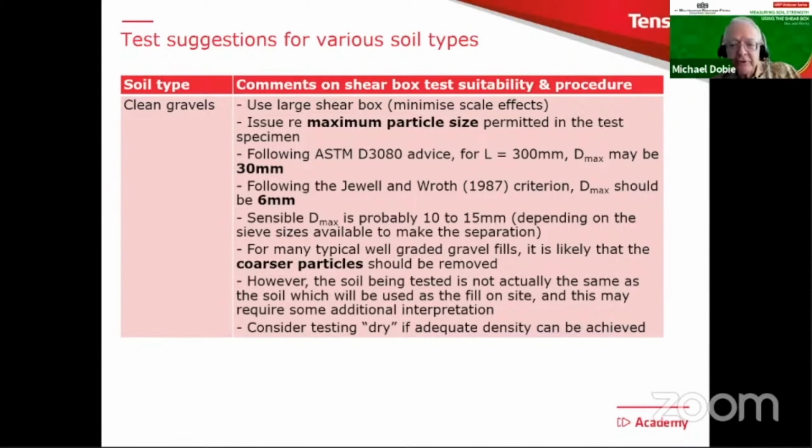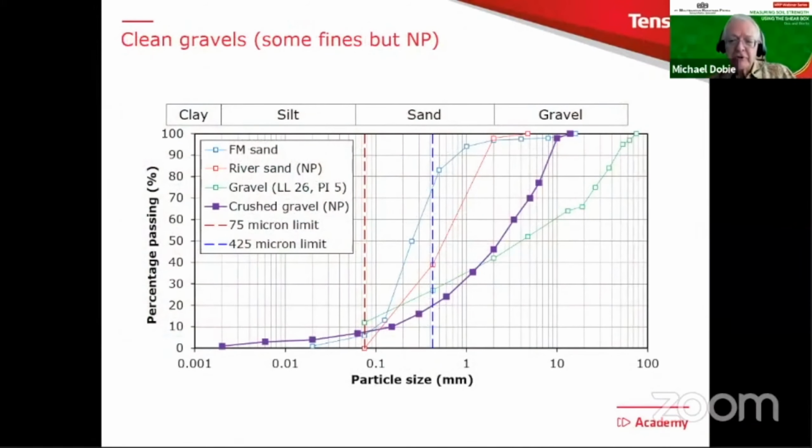And this, of course, means that in many cases, you're going to have to remove coarser particles. But again, as with the sand, if you can get adequate compaction or density, then you might consider testing it dry. So I'm just going to show you a result here. This is for a crushed gravel.